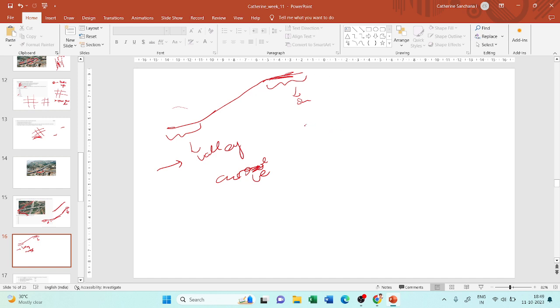And if you're traveling in this direction, you will say that this is my summit curve and this is my valley, or maybe you will even say that both are valley curves, because both are descending. And here you may call both summit curves, if you're traveling in this direction. But it is not the case. It does not depend on the direction in which you travel on your ramp. No matter which direction you travel, you will always have a valley curve at the lower end, and a summit curve at the upper end.